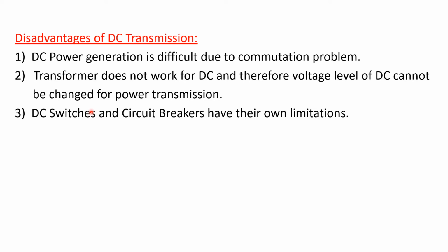And the second disadvantage is that transformers do not work for DC, because normally we use transformers in order to change the level of voltages. If we want to increase or decrease the level of voltages, then we can use transformers, but in DC transmission systems we cannot use them. In DC transmission system, the power is transmitted at a fixed level of voltage.